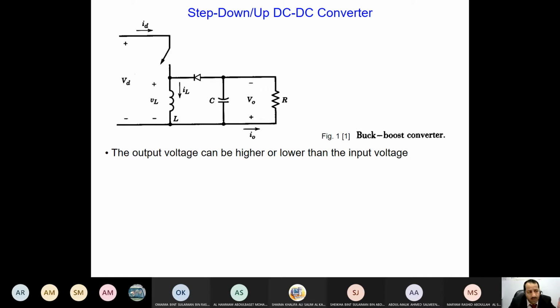So it's a matter of redistributing the components. You see here at the end, I have again switch, diode, capacitor, inductance. This is my load. But how I connect them will change the effect. And also let me remind you that for the buck converter, the relationship is D. For the boost converter, the relationship is 1/(1-D). This is the step-up effect, and this is the step-down effect.